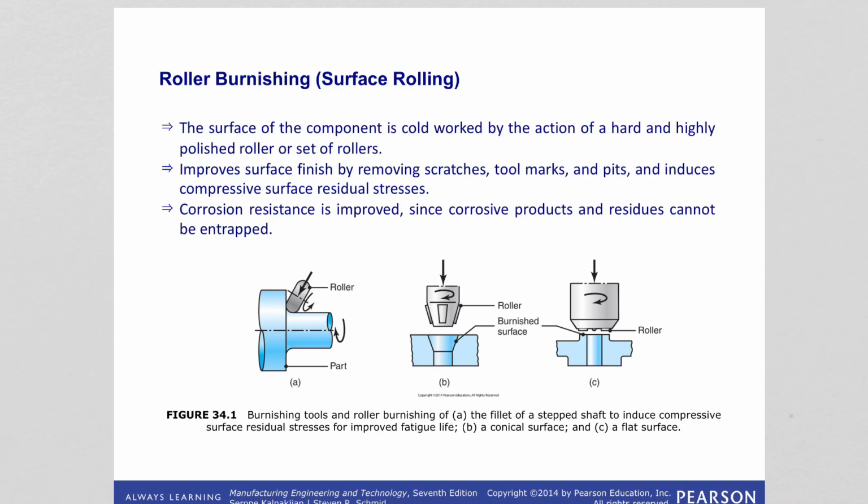It is just cold working without cutting or abrading the surface. It doesn't remove any material, but rather compresses, like ironing out the peaks of a metal surface into the valleys. So it is both improving the mechanical properties and also improving the surface finish.